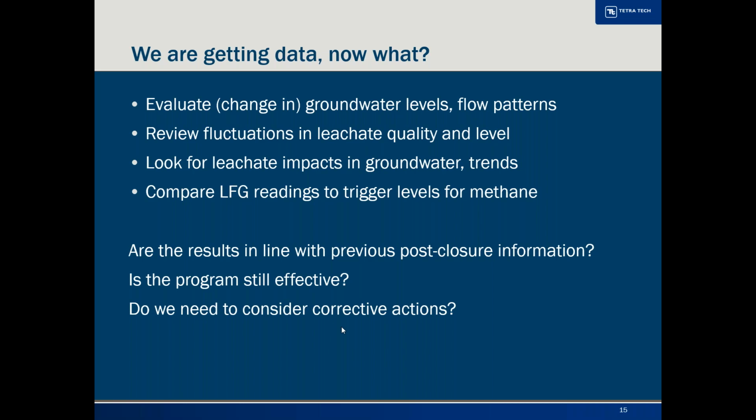And we compare landfill gas readings to trigger levels for methane. We have a fairly extensive network of vapor monitoring wells, like I said, and also a lot of them towards the residential areas. And when we have the data, we look at whether those results are in line with previous post-closure information. So if there's any trends, if there's any alarming new findings, and we figure out whether the program is still effective. As Mandy said, those closed landfills are not going away.